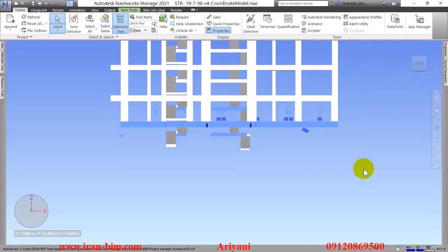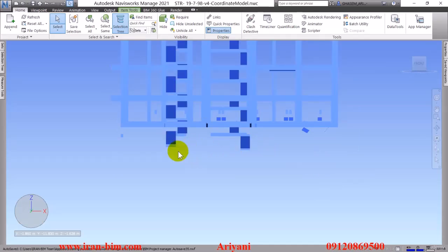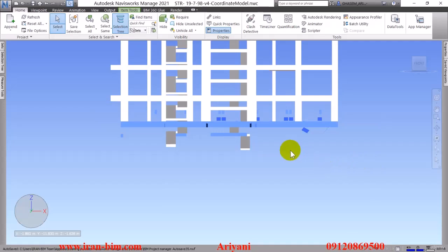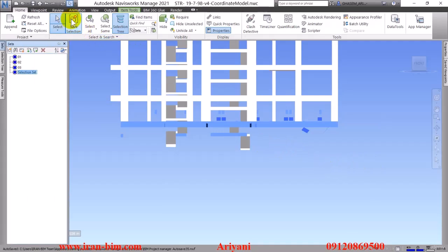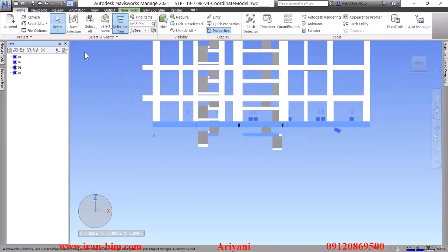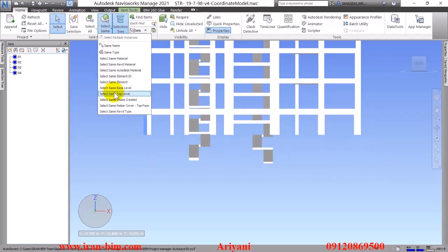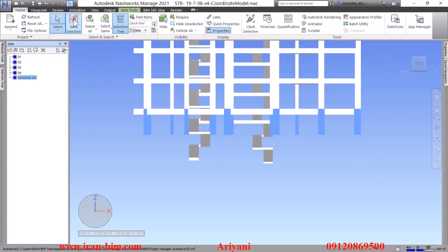Now this time switching to the front view, I'll select this part of the plan, but let's exclude the stairs as well, and name the selection of this one 04 and hide this one as well. Then going over here, I'll select this column and then select the same base level and create a selection for this one, naming it 05, and then hiding this one too.